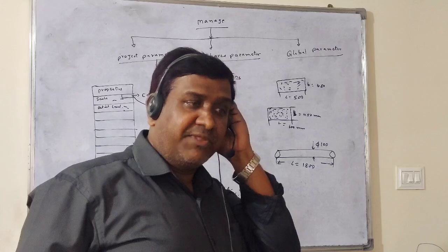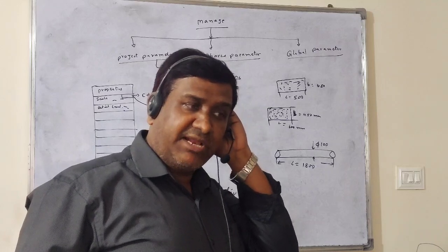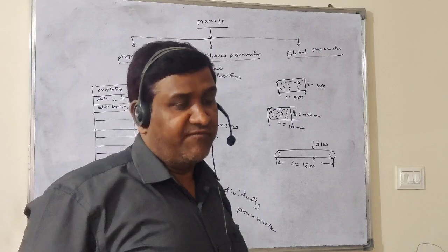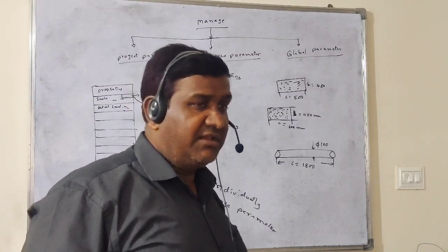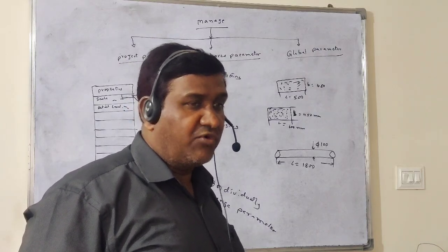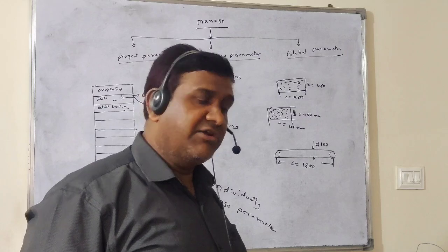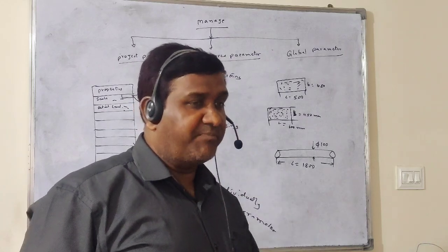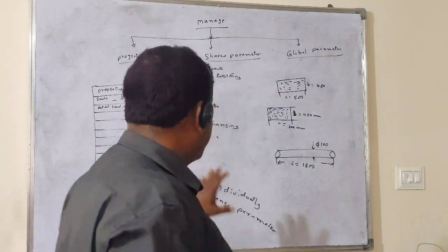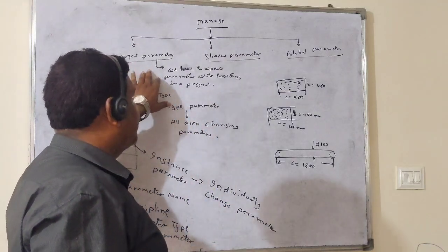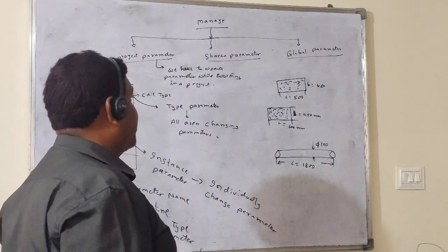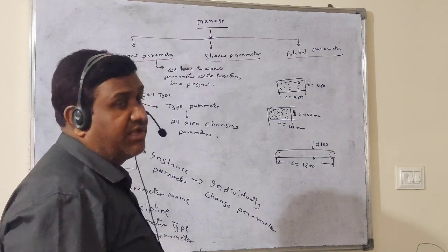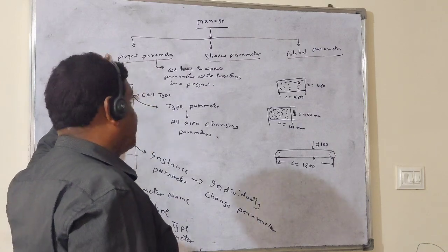If you are working some hotel project and in that hotel project you have given some new parameters, new information in that file. So if you close that file and if you open one more file, again you have to give the parameters, because the project parameters is temporary for the present project. So that parameters, when you are going to update it, that we will call as a project parameters, and it is only while working in a project, then only you have to update it. So that is project parameters.